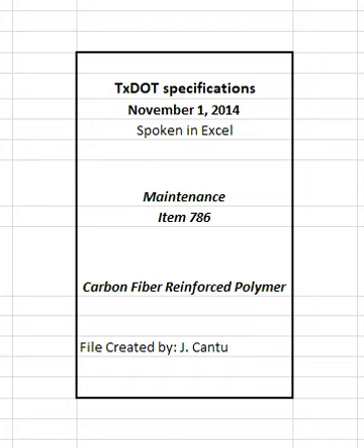Provide appearance coating recommended by the CFRP system manufacturer to protect the CFRP from ultraviolet radiation. Match the color of the protective appearance coating to the adjacent concrete. Submit a schedule of repair materials to be used including detailed application instructions. Provide manufacturer's product data sheets that include mechanical, physical, and chemical properties for the proposed primer, putty, resin, saturant, carbon fiber, and protective appearance coating.